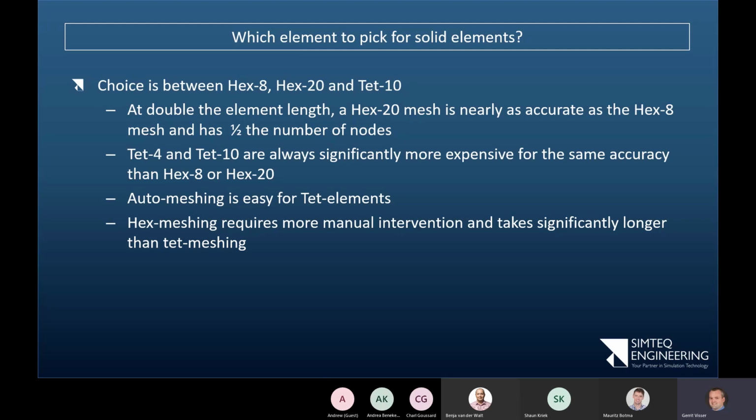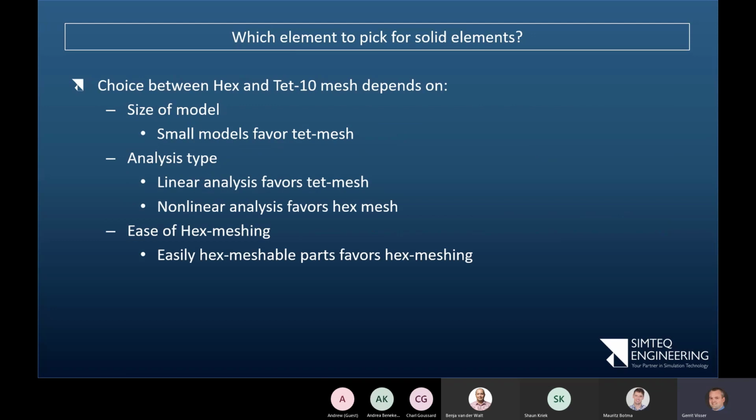The problem with that is you can't mix first and second order elements easily. So if I have an X8 core, I end up having to go to TET4s on the skin, and that's where the high stresses are. If I have an X20, I'll go to TET10. So I use this element because they're efficient, but now suddenly I need fine elements there. Effectively, it's not as great as it sounds, but it is a convenient in-between method compared to using purely TET10s, or the extreme expense of, in some cases, meshing the X8 and the X20.